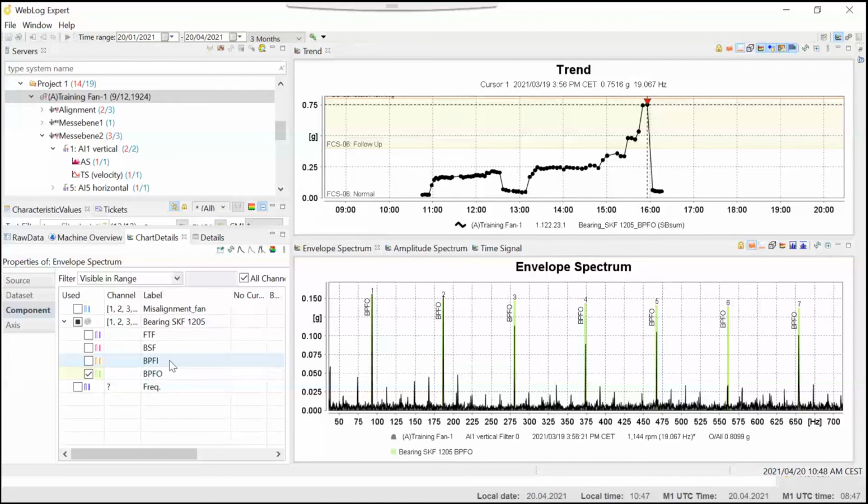It would depend on the type of failure that you were looking at. So mostly with a rolling element bearing failure, you could probably say, yes, that's likely to be a rolling element bearing problem, but most systems have at least one bearing at each end, and sometimes they have two bearings at each end, one thrust bearing and one radial bearing. So you need to be able to distinguish which bearing it actually is. And if you have something like a gearbox, there'll maybe be 6, 8 bearings in a gearbox. So there are quite a lot of decisions to be made to find out the right bearing to change. Okay.